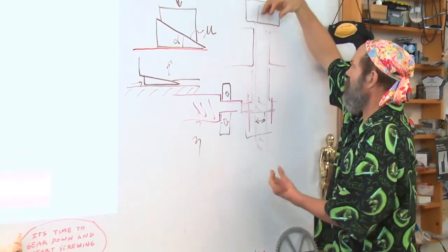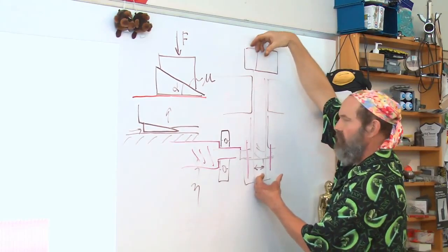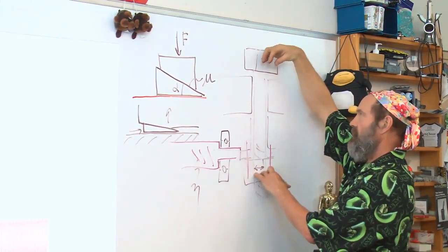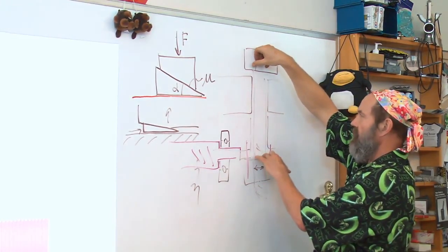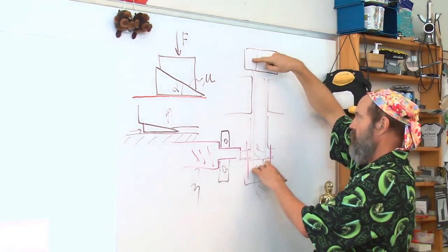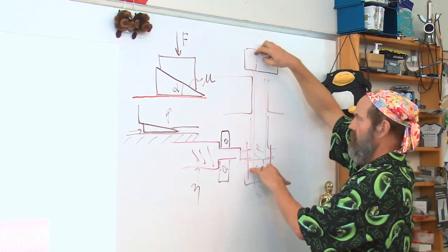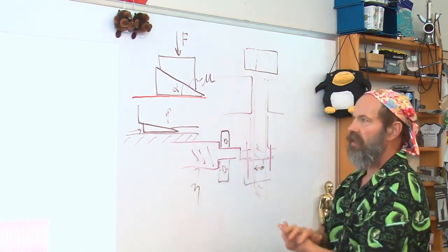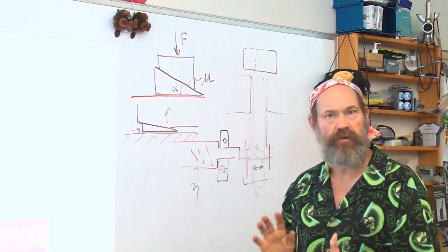So when I'm twisting the shaft, it's stretching it as it goes to compress the part. I'm applying torsional stresses due to torquing the bolt, and I'm also applying tensile stresses because that torque acts through the lead, and the nut doesn't want to move, so it stretches the bolt. That detailed stress case is handled by, for example, the von Mises stress criteria, and you have to consider both of those effects.